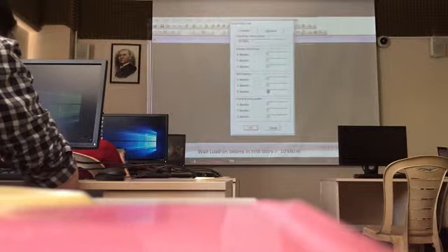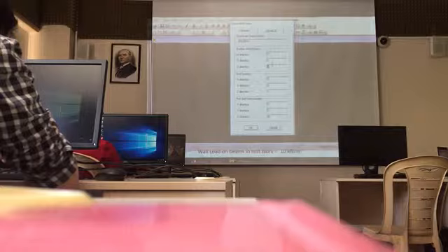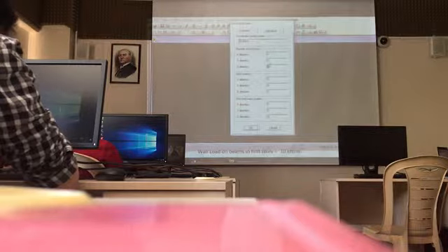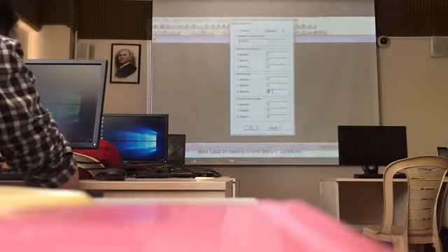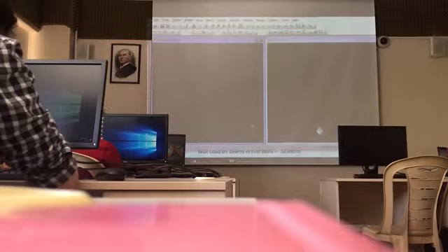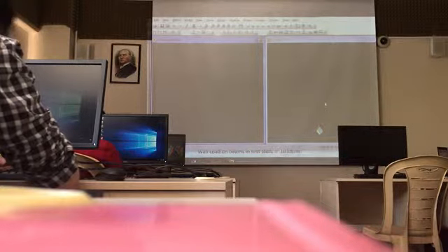Okay, let's use the replicate command to generate the other story. Select this 2 and this is 3. Okay, 3.5 then. Okay, this is 3.5, but after I replicate it, I'm going to move the joints downward, or move the grid line.